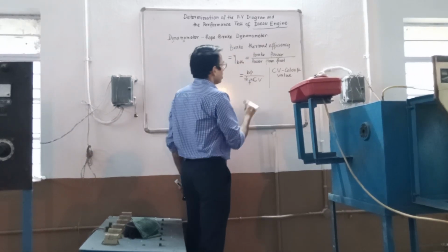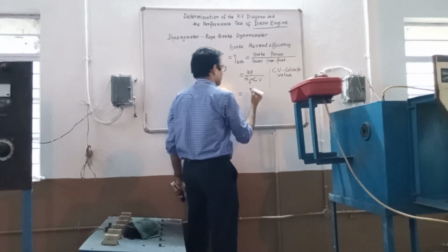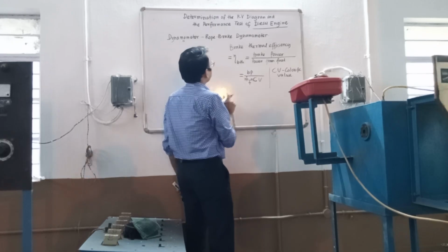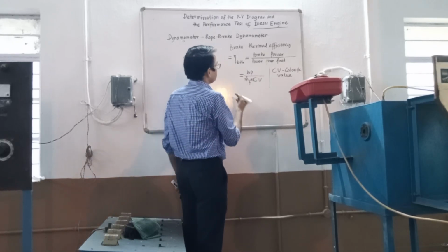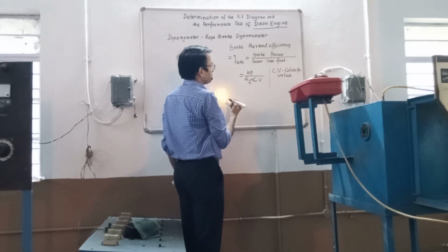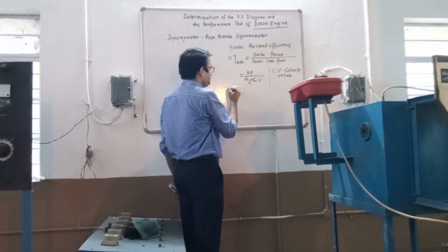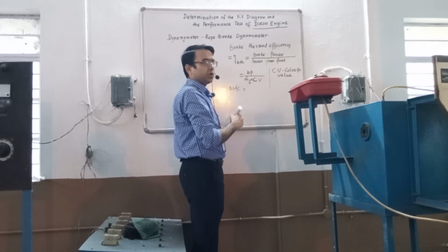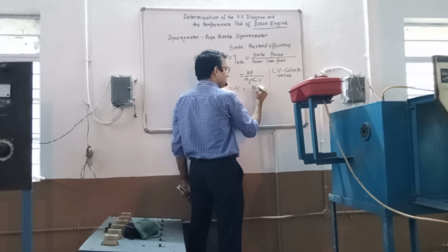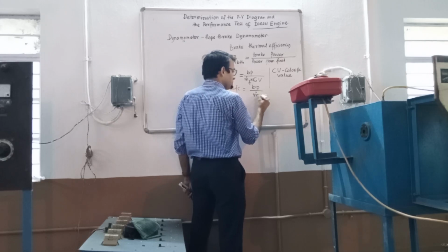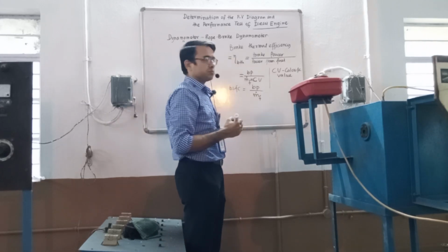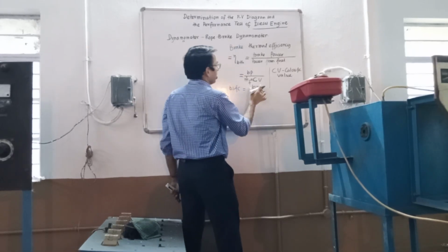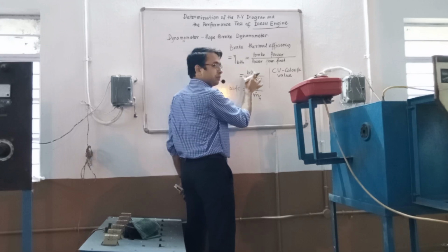Calorific value. Now therefore we can calculate this. Another thing. Next we will calculate the brake thermal efficiency. I'm sorry, the brake specific fuel consumption. Brake specific fuel consumption is brake power divided by mass flow rate of fuel, or rate of fuel consumption. So that we can calculate BP. Because we have calculated BP, we can calculate this.